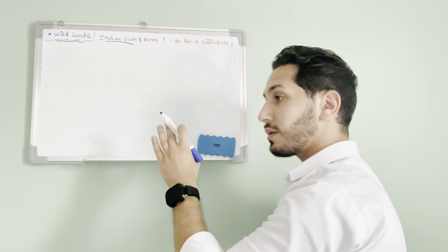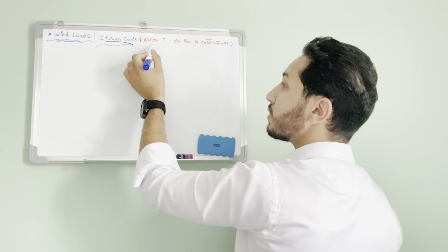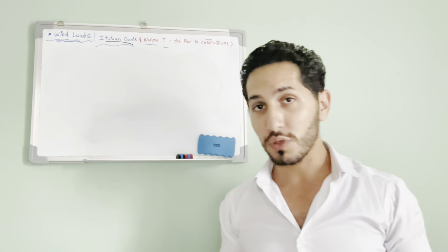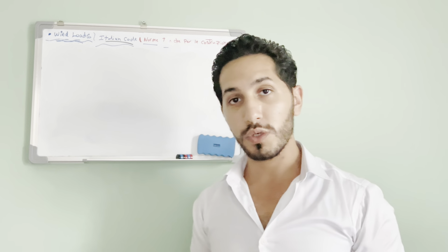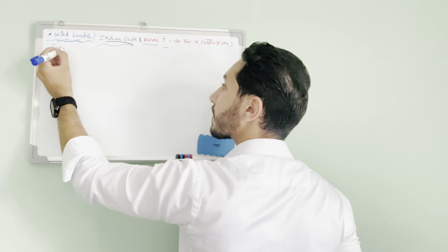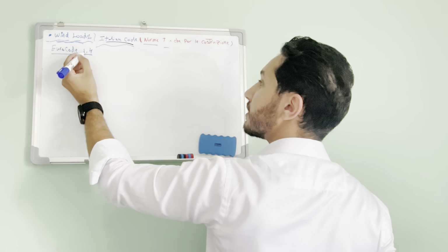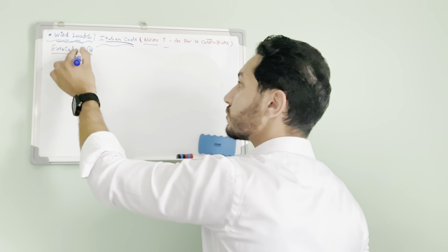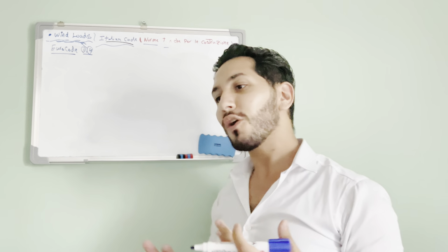Before we start, we need to figure out that we are using the Italian code. The Italian code is called the Norme Tecniche per le Costruzioni, which is the technical standards for the constructions. And it's following the European code, which is EUROCODE, so this is EUROCODE part 1.4, since part 1 represents the actions on the structures and point 4 refers to the wind load. Okay, let's just go straight away to the topic.